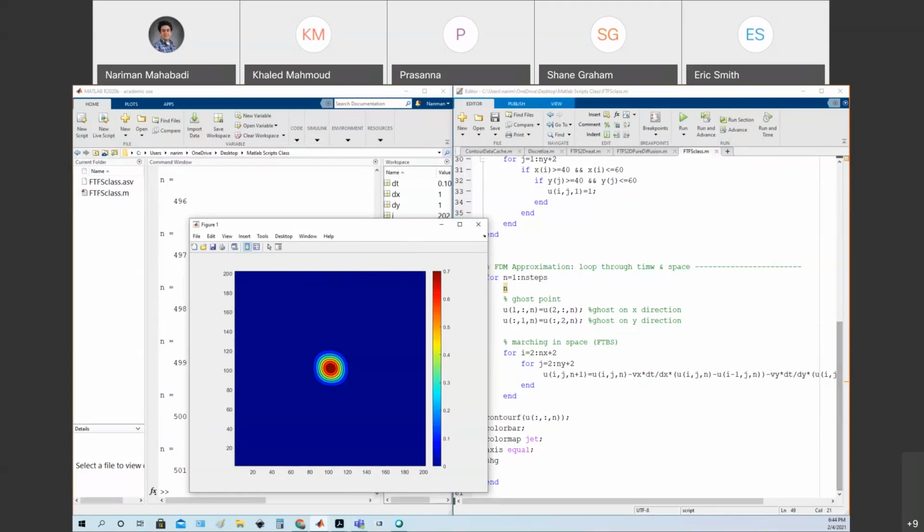Okay, and Giovanni, you asked what exactly do you look for to determine if it's stable or not? I think I briefly explained this before writing the codes. The von Neumann method says that if your unknown function, let's say a concentration, has a maximum value of 1, and I get some value larger than 1, this means that it's unstable, and it's exponentially increasing.